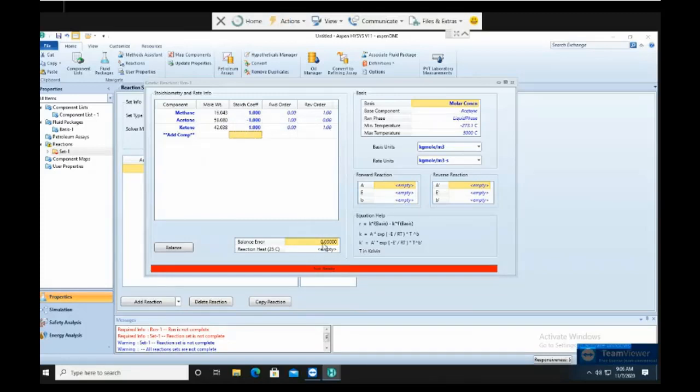Okay, now it's empty, this is fine. Then we have the information in the question: the forward reaction for alpha, A is 8.2 to the power of 14, so we put E14, and the activation energy 2.85E5. So we enter. So it's ready.